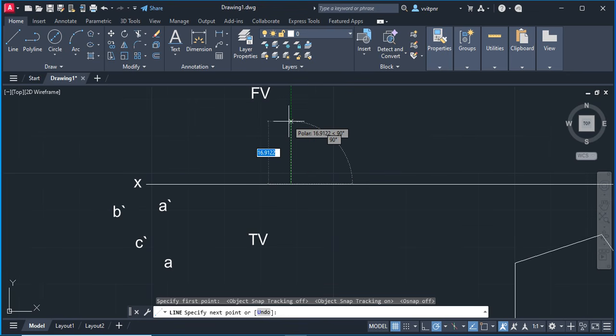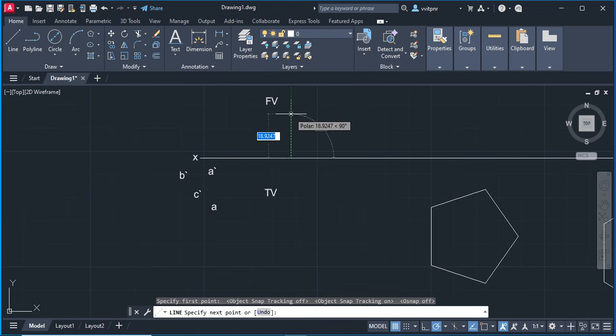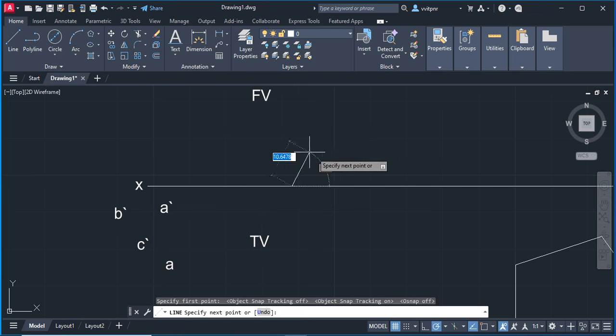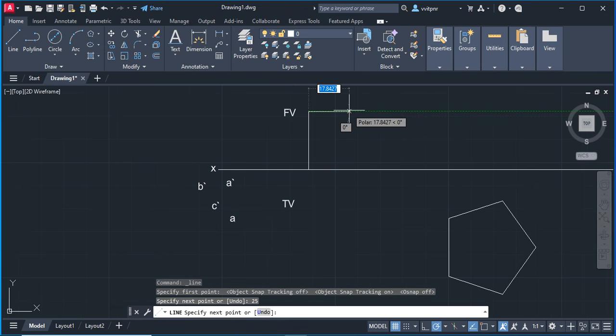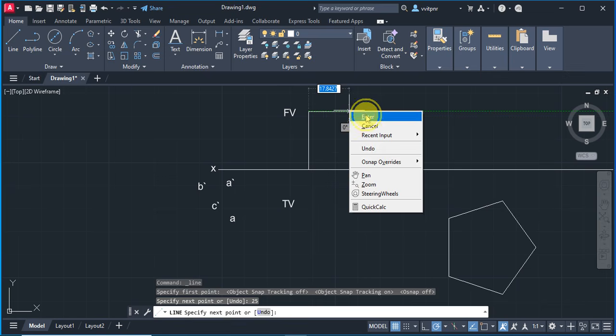And mark here. Let us say you want to draw the front view image with HP distance as 25. Simply draw this line perpendicular to XY. It was showing a 90 degrees angle. So draw this line at an angle of 90 degrees, with 25 length. Enter 25 and press the enter button. It was drawn with 25 length.